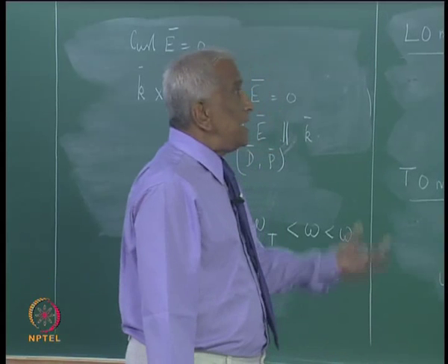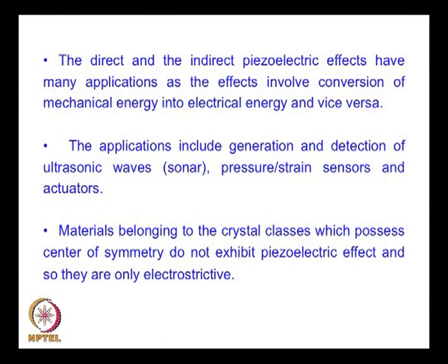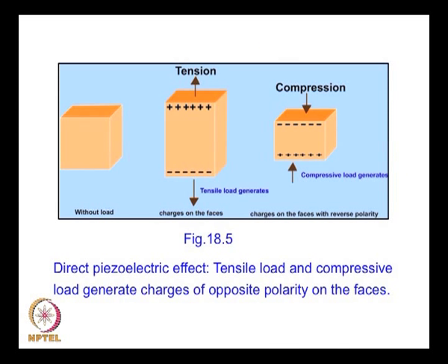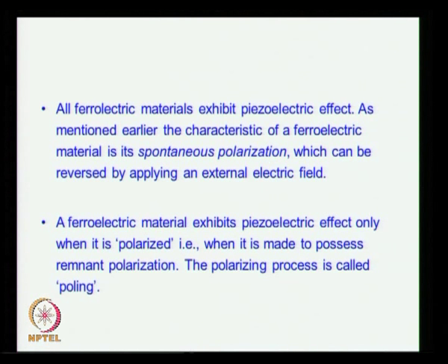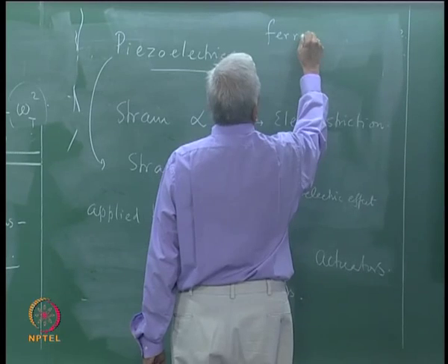Usually materials belonging to crystal classes which possess a center of symmetry do not exhibit a piezoelectric effect because of the linearity. So, it is only the non-centrosymmetric crystals which produce the piezoelectric effect. That is shown in the next couple of figures, the direct and the indirect piezoelectric effect. And we have already discussed ferroelectrics. All ferroelectrics display piezoelectric effect.